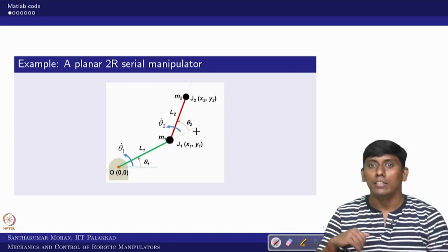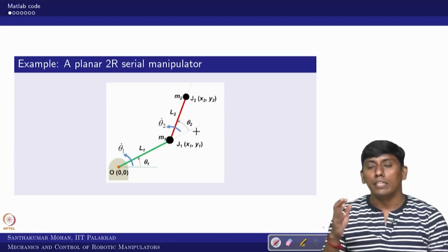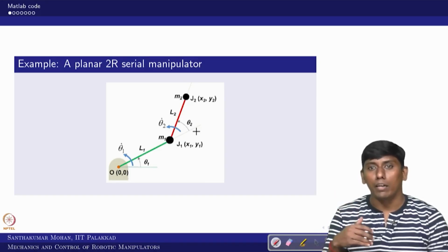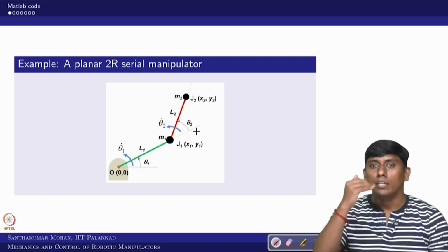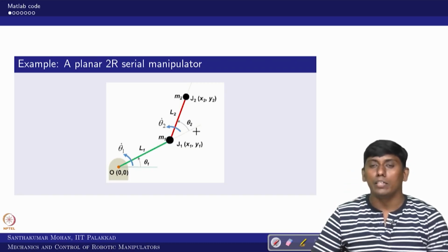These we have all seen. Further, we have seen how to propagate the angular velocity and linear velocity if we know the base angular velocity and linear velocity. We always assume that the base is fixed. These codes we have seen in the kinematic model derivation and the differential kinematic cases, or the velocity propagation model.